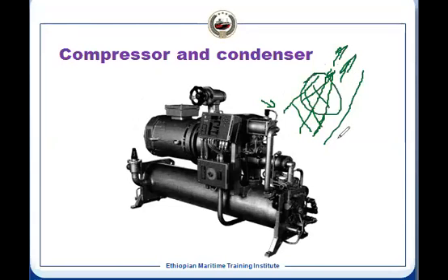Now there are different lobes. Now, if there is a slide valve at the side, this is the slide valve, and this slide valve is covering the ports, which is the outlet, the delivery of the compressor. And as this slide valve moves, suppose we want 100% capacity, it will move this way so that it will allow the flow through this. It means it will get compressed completely and then come out. And if we want it reduced, then what will happen? It will take outlet from here.